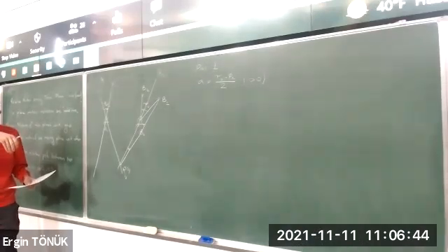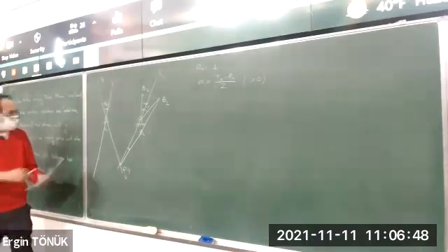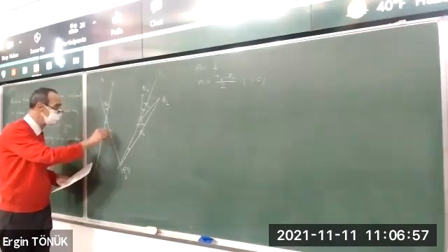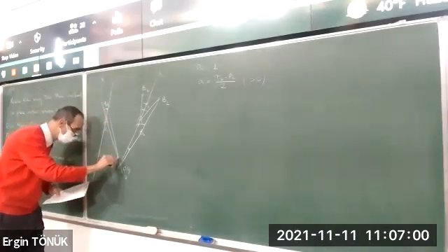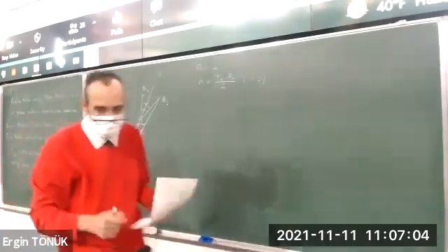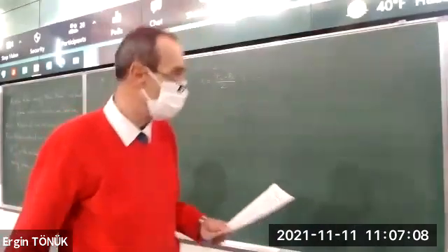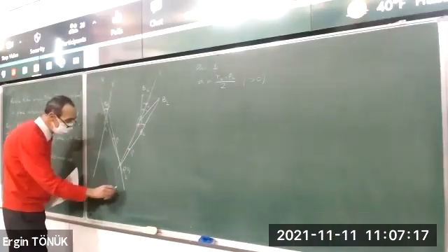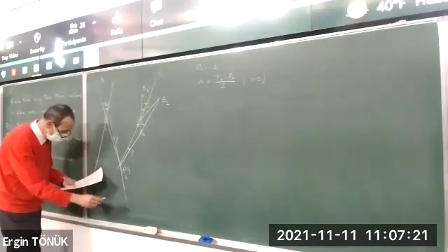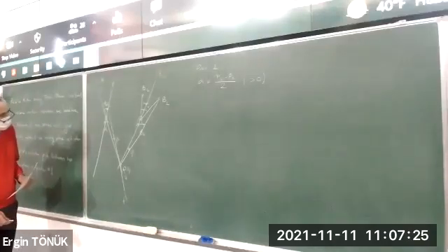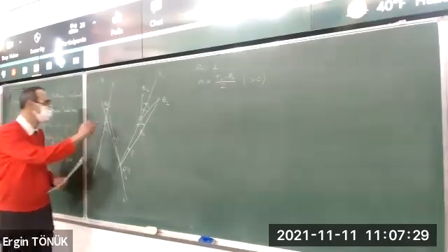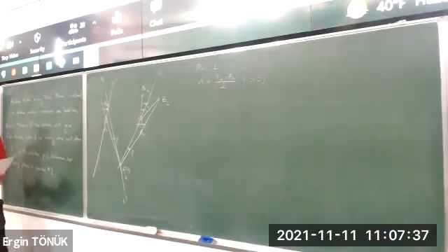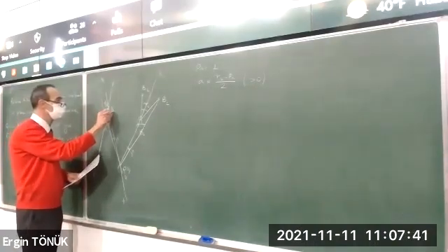It's clockwise. So I'm going to draw the other angle, A0, R12, X in the clockwise direction, like this. So these two angles are equal. Let me see what I have called them in my notes. Gamma. So that angle is gamma, the same angle, gamma. So that is line X, and point A is at the intersection of the two, because cranks subtend the same angle at the pole. So this is going to be my point A1.